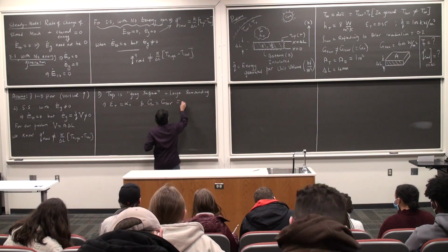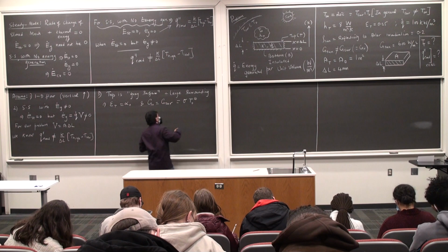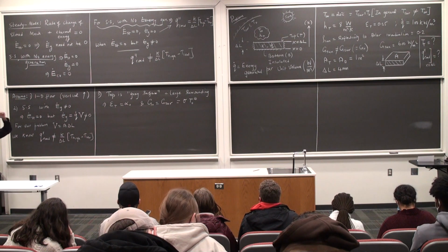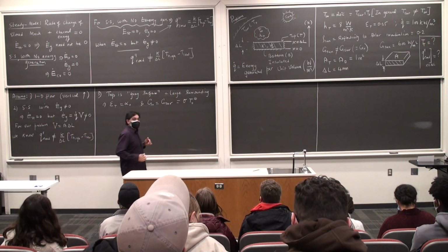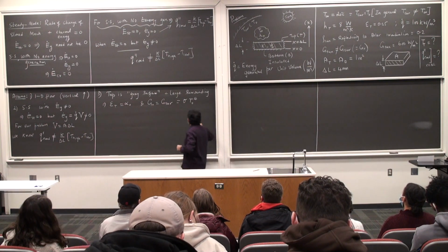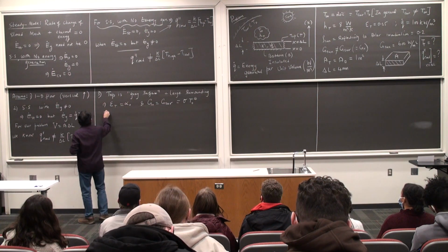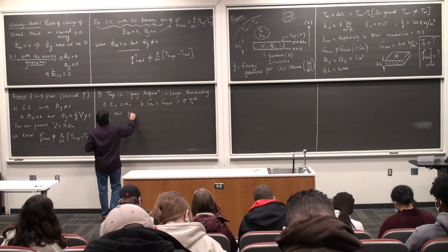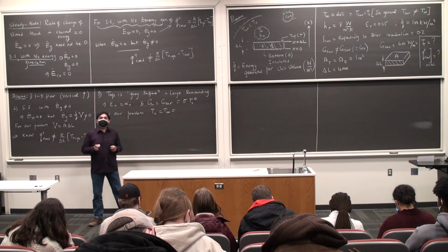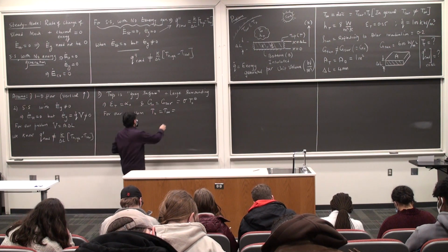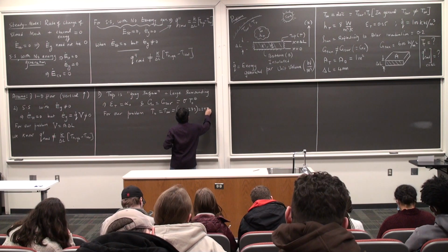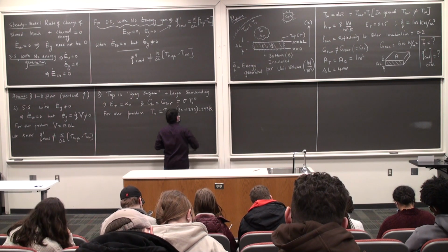This is sigma T naught to the power 4. And we are also in turn assuming that T naught is the same as T infinity because we are not given any other information. If you are specifically given information on the surrounding temperature, please use that. Okay? For us, it is 20 °C. Convert everything into Kelvin. So 20 plus 273, 293 Kelvin.